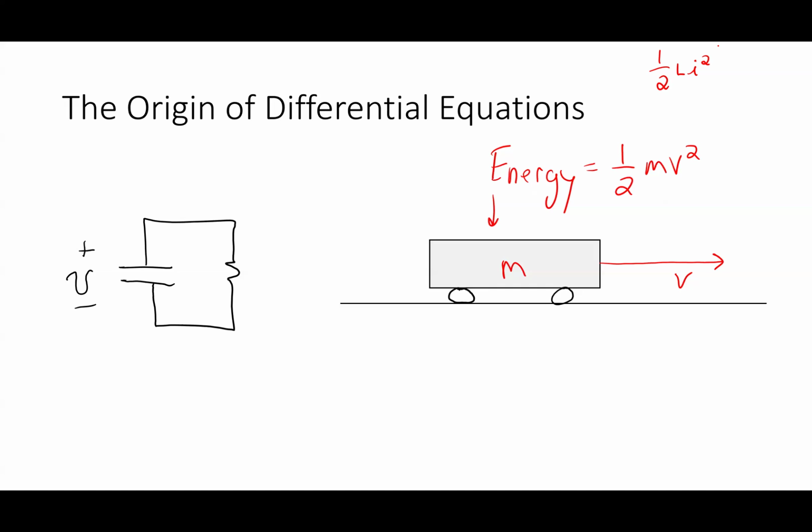Well, it'll spark on you. I mean, it's going to discharge, yeah, but it'll spark as soon as you stick a screwdriver across it, because the energy stored in the capacitor has to go somewhere, so it becomes light. It's got no choice as to what to do. So what that's saying is if I have an energy storage element, I cannot change its energy instantaneously. It takes time for it to change. It has a sort of trajectory from one state to another.